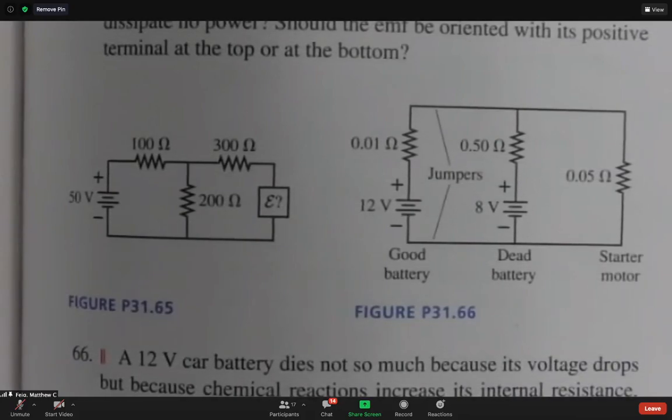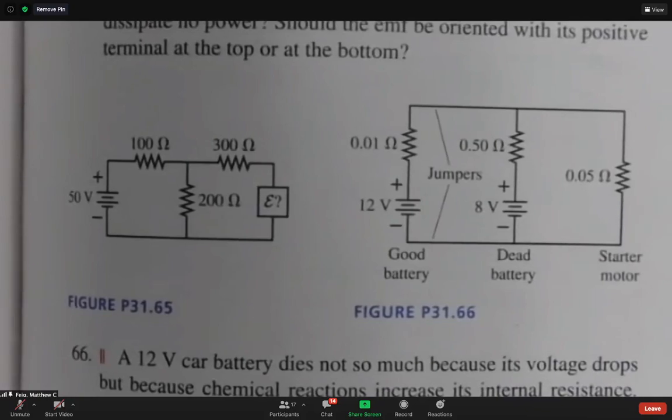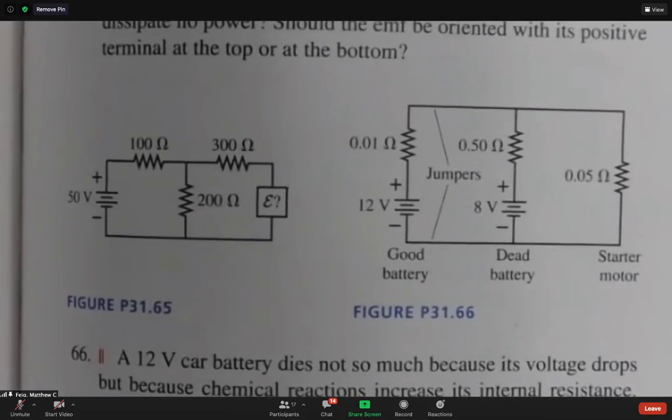No power. No power in a resistor. What would no power in a resistor mean? No current flowing through it. So in general, there'd be 3 currents in this circuit, right? In general, there'd be a left current, a middle current, and a right current. And in general, every resistor would probably have a different current amount. And what they've gone to is they've dialed things around. It's like we're dialing the voltage up and down on the right battery, and we're observing the current on the middle branch until we get to 0.